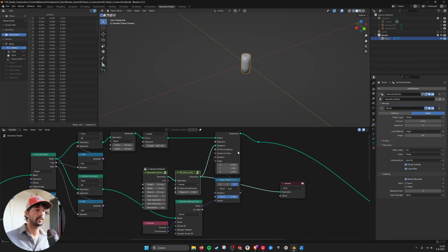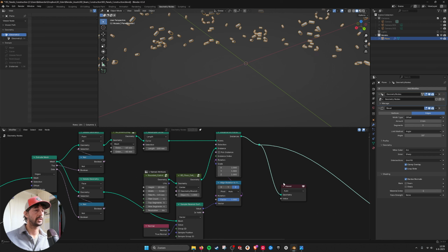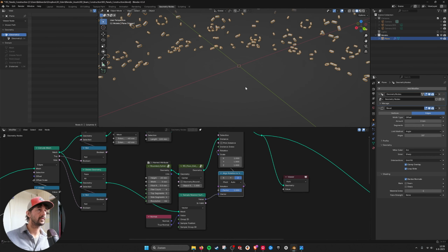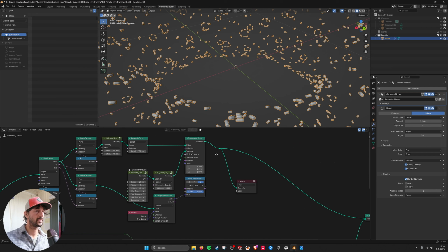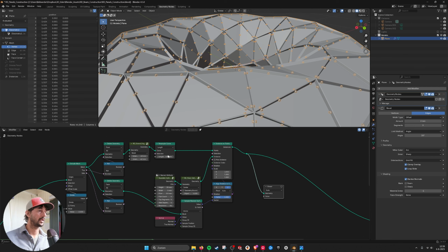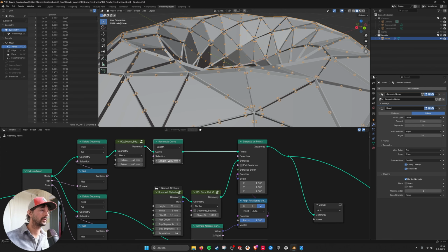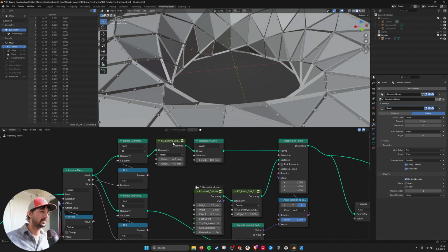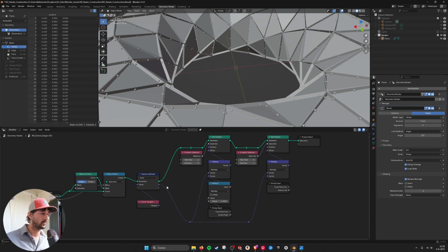I'm flooring it, centering it, so it's right in the middle, and then I'm using it as an instance with the alignment of the Z, and I'm using the vector normal that I sample from the closest surface. So if I then take this away, you see that all the bolts are here aligned. I'm also using a resample node for the curve, so I can give it less or more bolts. So if you get larger faces, then you get more bolts, leaving this at 100, and then you see the distribution.